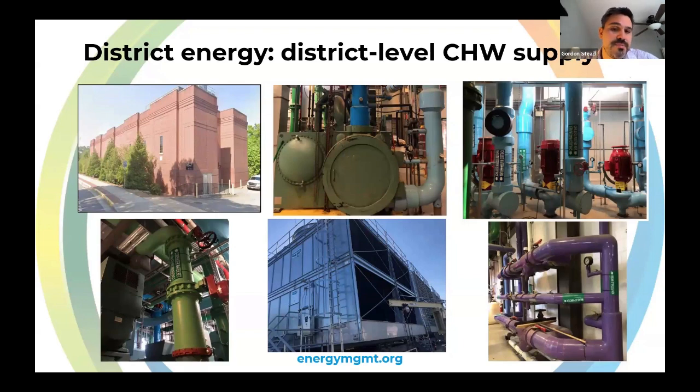At this time of year, it'll just be chillers in that plant which are working. But as part of that loop, you've got a bunch of distributed chillers in buildings. In the summer, as the call for staging goes up and up, by mid-July you've got everything running, well, N+1 redundancy, but essentially everything. And then in other loops, it'd be more just distributed chillers.